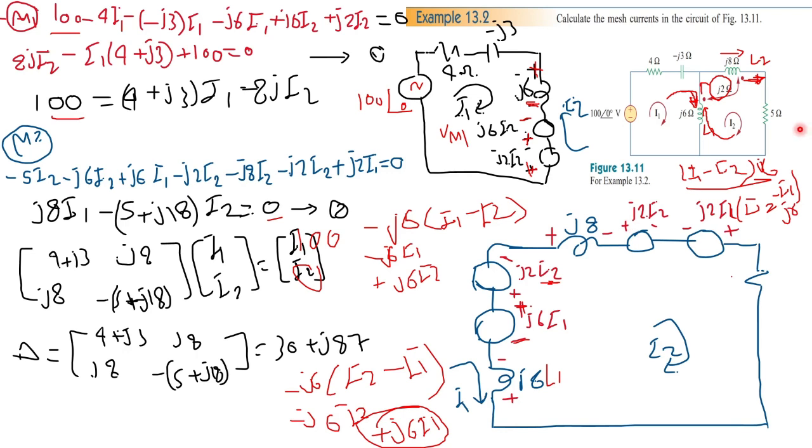So we have three voltage drops: one on the resistor, two on L1, one because of I2 minus I1, and then another voltage drop around L2 because of I2. Then we have a mutual inductance voltage induced, mutually induced on L1 because of I2 passing through L2. And we have two mutually induced voltages around L2, one because of I2 passing through L1 and one because of I1 passing through L1.